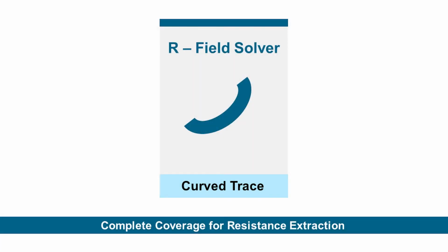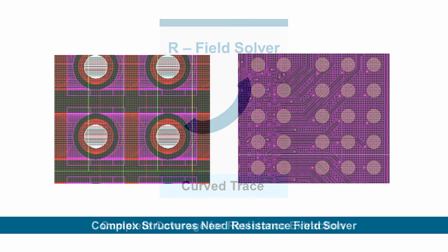The resistance field solver, or RFS, uses a refined mesh analysis approach for resistance calculation to provide accurate resistance extraction for any shape of geometries, including non-Manhattan shapes with many holes. To allow resistance calculation of planar arbitrarily shaped geometries, a 2.5D meshed approach will be used.